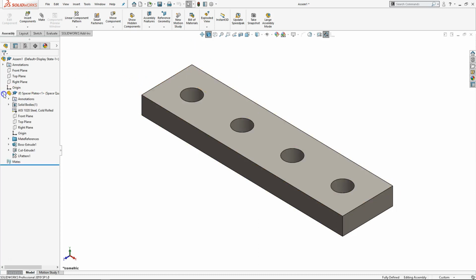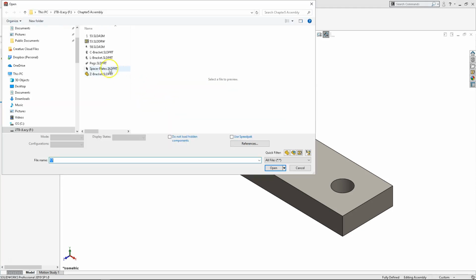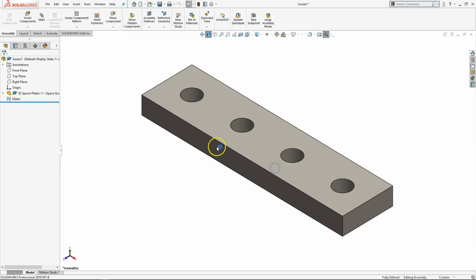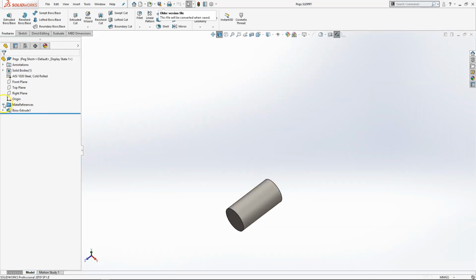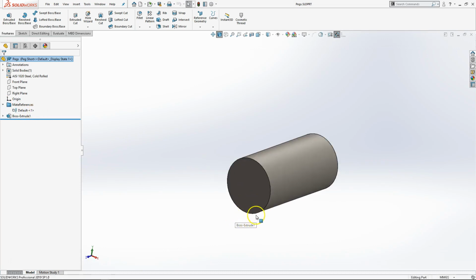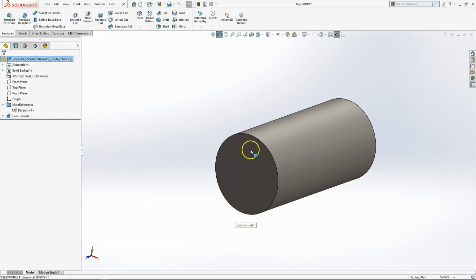And we saw, I think it was on the peg, you will be able to set a mate reference that has a default setting. So when I drag this in or I move it around, it will automatically snap. And as long as I keep holding down the left mouse button, I can hit tab to reverse it.